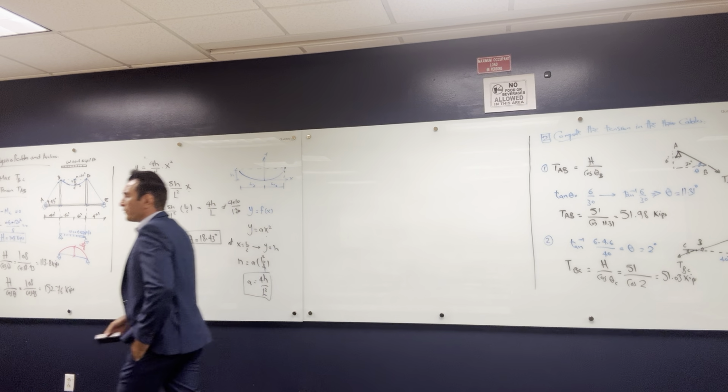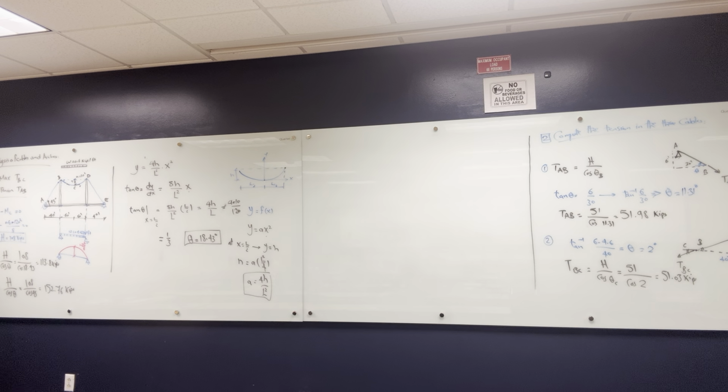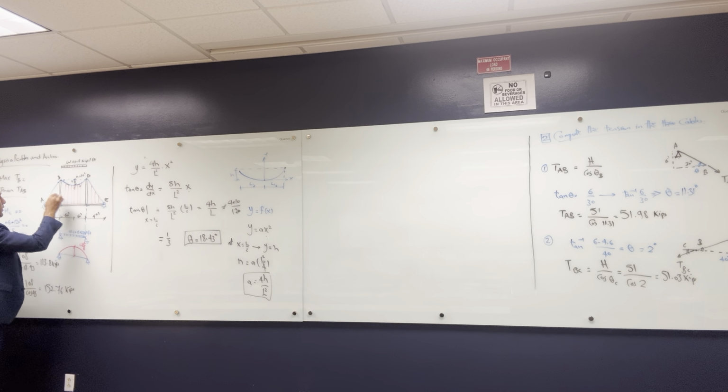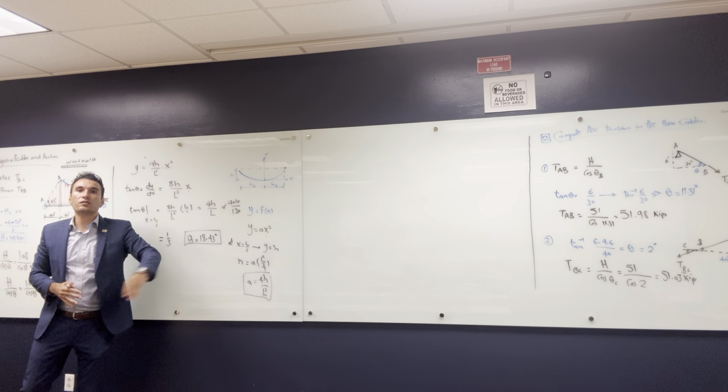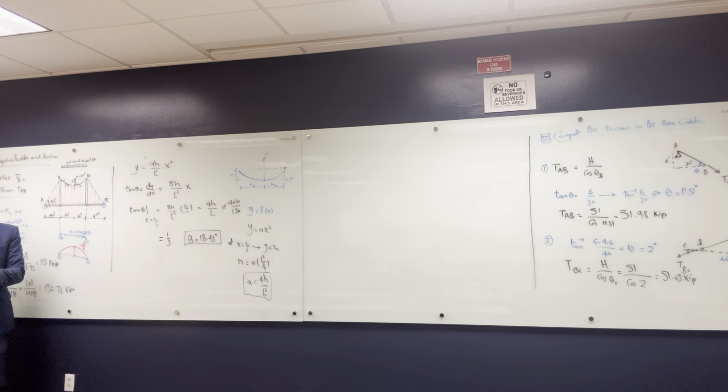By the way, in real life, when you solve a stay cable bridge, you're not going to be given this load. The thing is, you're going to have small cables holding this bridge from here and from here, and you're going to have a load here and a load here. So what we do is find how to transfer this load to this one. Either you put it as a concentrated load, but usually you have hundreds of cables and it's almost a distributed load. Or when you solve in the software, you put them as concentrated loads.